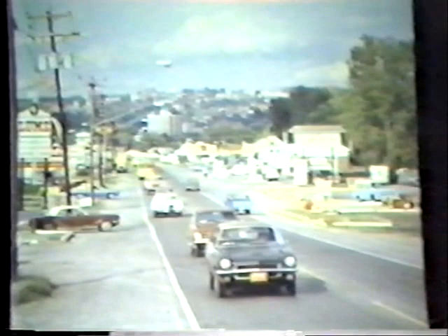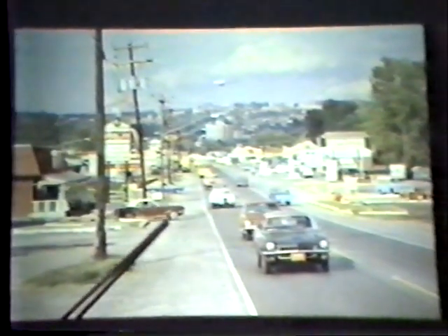But when you have a road, say in an urban area like this one, driveways, McDonald's, and so on and so forth down the road here, parking alongside the road, very small gaps between vehicles, quite a directionality, more traffic going this way, not so many vehicles going the other direction. All of these factors interact to reduce the number of vehicles per hour that you can get going down a road.